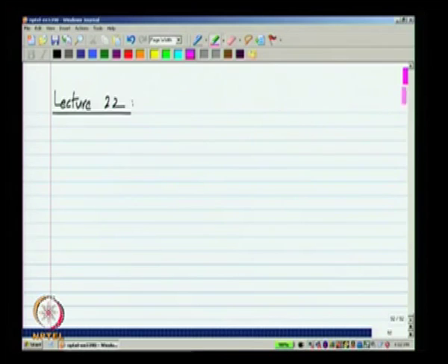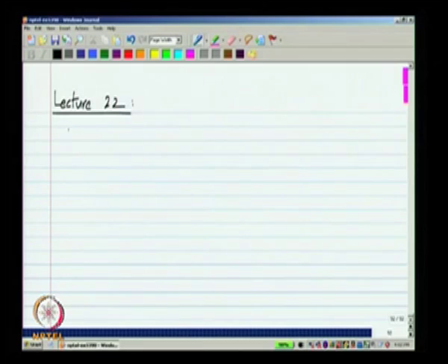We also discussed the behavior of the MOS transistor when the VGS is below the threshold voltage, and we saw that it turns out to be an exponential. Now, as I also mentioned in the last class, the real model of a MOS transistor is very complicated. So, you have to use a simulator to gain a better understanding of the MOS transistor. So, what I suggest that you do is take it as an exercise to get hold of some MOS transistor models. In fact, some models are available from this website.